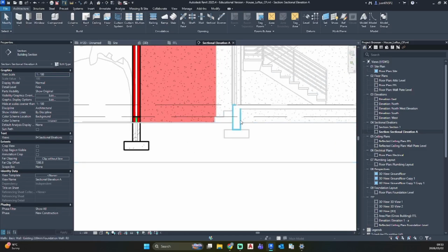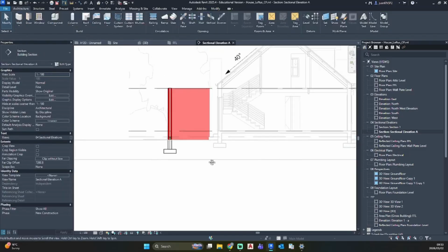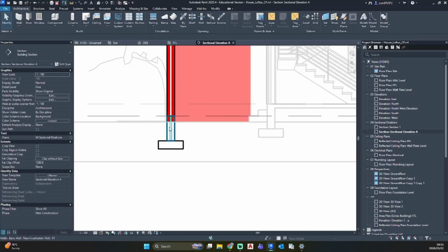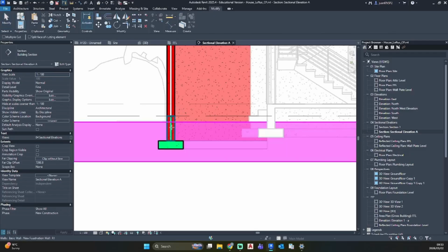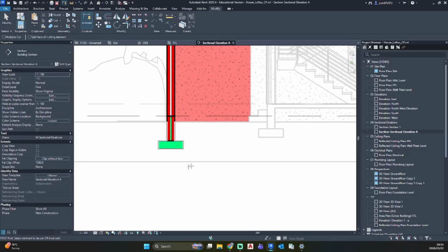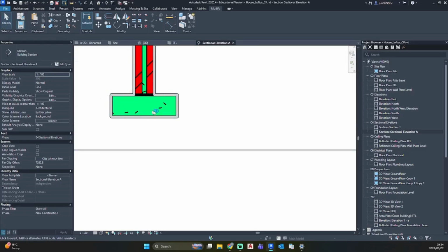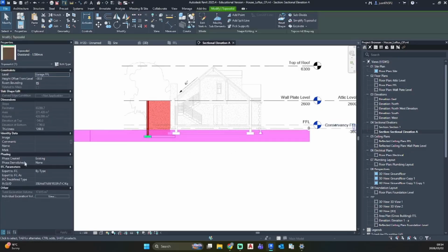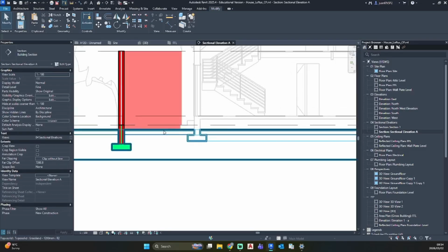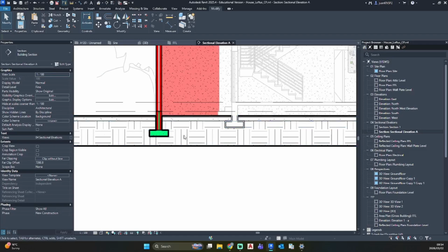Let's see this height. Okay, also 750. Okay, so now let's cut. Let's say to modify, cut, select the site, select the wall, select the site, select the foundation, so that we have a clean cut through it. But as you can see, our site isn't showing any cut patterns. That's because it's drawn in the existing phase. So for drafting purposes, you can change it to new construction and you will get this nice cut pattern.